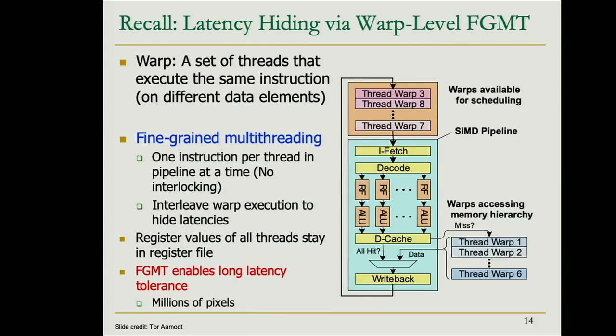This is what the warp scheduler does when it goes to this L0 or L1 instruction cache and reads one instruction and starts decoding it to issue onto the lanes. So we decode it, and then we have these scalar pipelines in parallel, and each of them represents one of the SIMD lanes inside the GPU core.